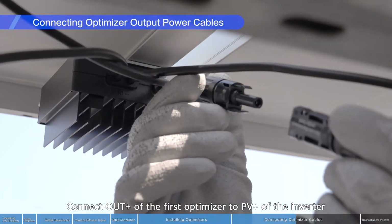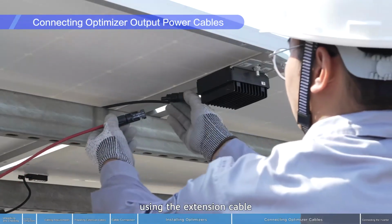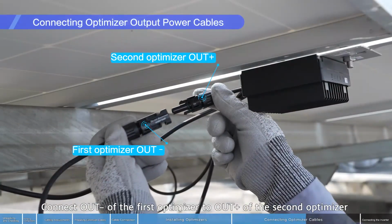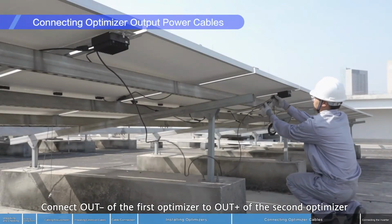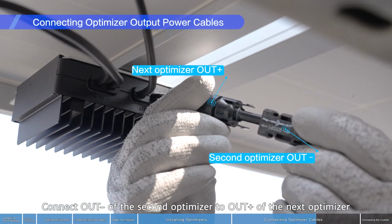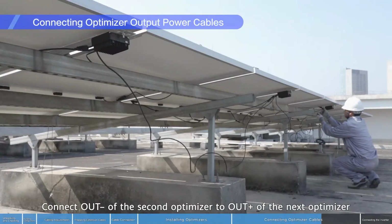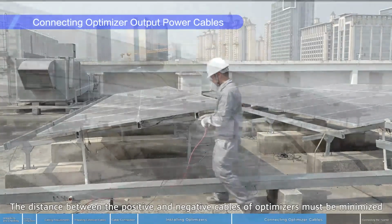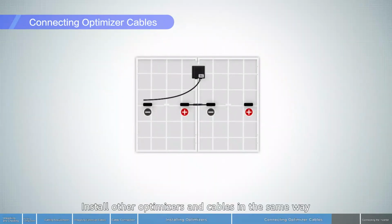Connect out positive of the first optimizer to PV positive of the inverter using the extension cable. Connect out negative of the first optimizer to out positive of the second optimizer. Connect out negative of the second optimizer to out positive of the next optimizer. The distance between the positive and negative cables of optimizers must be minimized. Install other optimizers and cables in the same way.